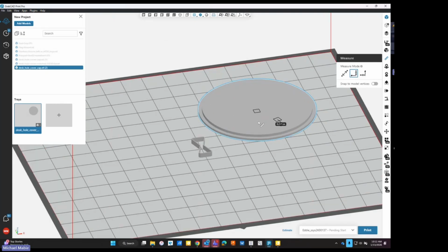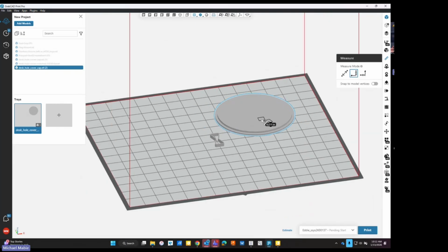So in some cases, I've actually seen where the larger the footprint of a part, even though based on our number category, this would say to build it in normal, you could get away with running this in brick mode if you were concerned about it lifting.